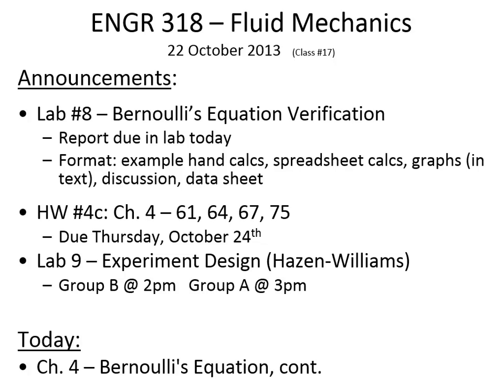What do you label the vertical axis? It has units of length. And so you don't label it as length, you just label it as head. Right, head. Because this is pressure head, elevation head, and velocity head. Those are the three terms that are going into EGL.